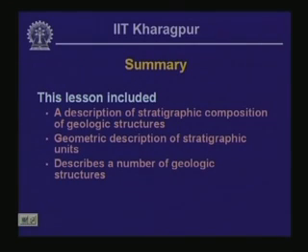There could be glacial outwash deposits that are comprised of sand and gravel, or there could be glaciolacustrine deposits that are fine grained deposits underneath glacial lakes. Okay, that in a nutshell summarizes different types of landforms. We looked at descriptions of different stratigraphic units, we looked at how to define them geometrically, and we listed a number of landforms that are often encountered in the branch of engineering geology.